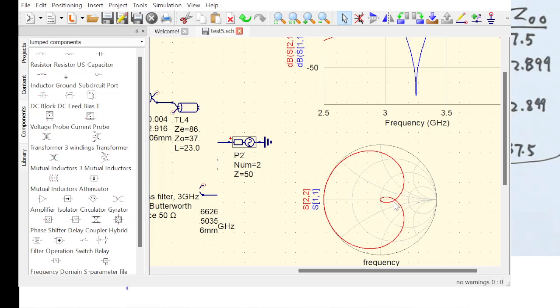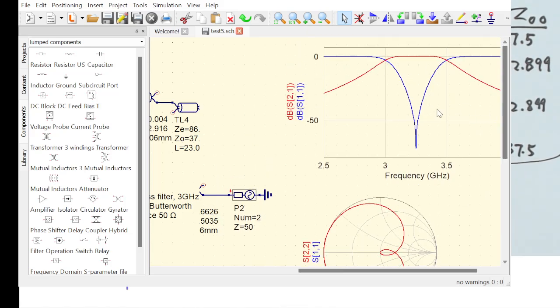And in this little loop here, we will have the impedance closely matched enough, but they are not exactly matched. But this is good enough for wideband matching. This is a very good quality match, and you can see from the S11 of this graph.